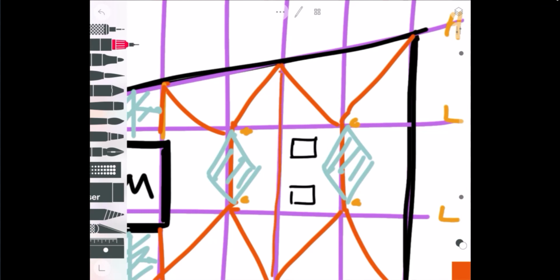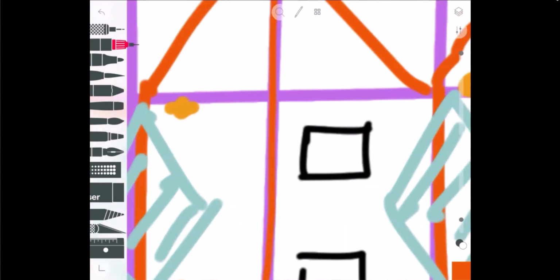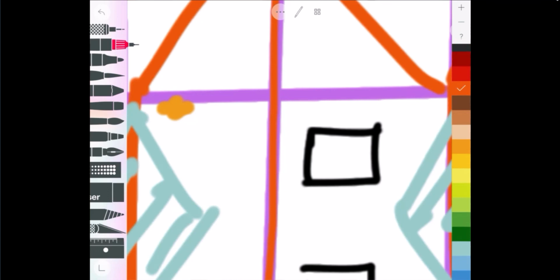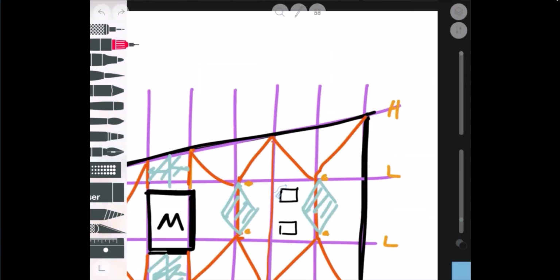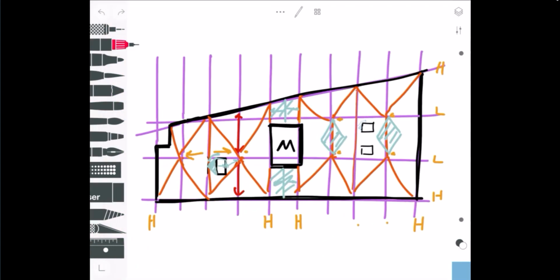And then in this case, if we zoomed in here, you would build a little insulation cricket in behind there, like so, so that water can flow around that thing and get down here and flow down like that. So those are called crickets, and they're sloped insulation usually, and you want to identify those areas on your roof plans so that the roofing people that are bidding on the project know what they have to deal with. And that's in a nutshell how you kind of approach sloping a structure.